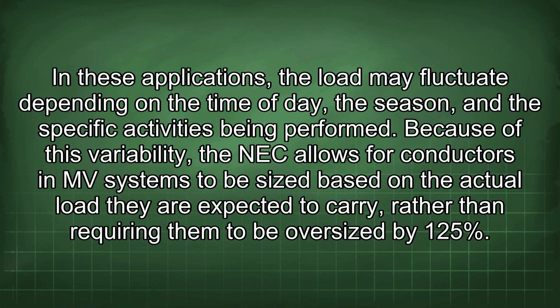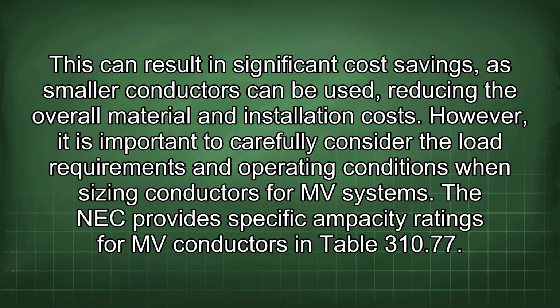Because of this variability, the NEC allows conductors in MV systems to be sized based on the actual load they are expected to carry, rather than requiring them to be oversized by 125%. This can result in significant cost savings, as smaller conductors can be used, reducing the overall material and installation costs. However, it is important to carefully consider the load requirements and operating conditions when sizing conductors for MV systems.